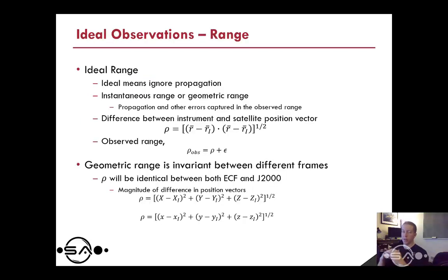Because really now we're starting to get into the real part of orbit determination, and I kind of alluded to this last time, but even though we're simulating observations, we're still starting to talk about observations minus our computed state, right? So we observe the state and we subtract it from our computed state or our model, and that gives us some residuals. And really what we want to do in orbit determination is reduce our residuals in order to give us a better prediction of what the state's going to be, right? Or what it has been in some cases.